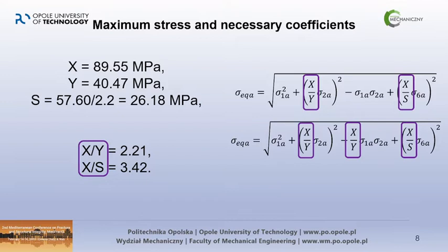Theoretically, in the standard, it is written to divide it by 2. However, in the article, they also proposed that if you want to analyze how strong the material is for shearing, you should divide this strength in the 45 degrees cutting specimen by 2.2.